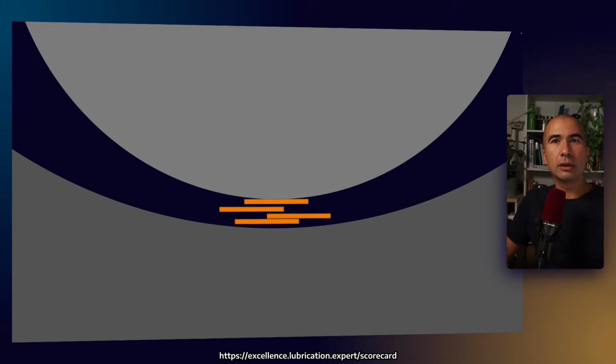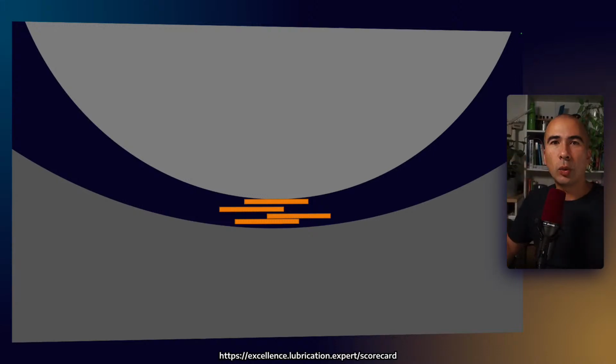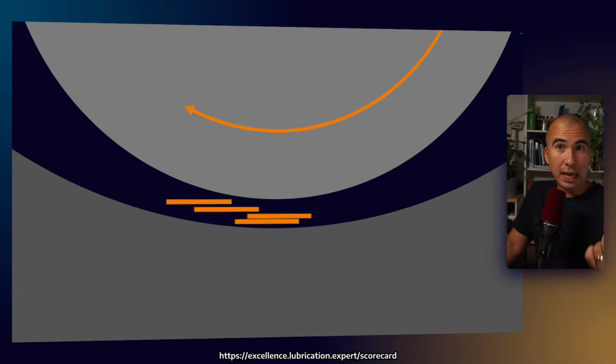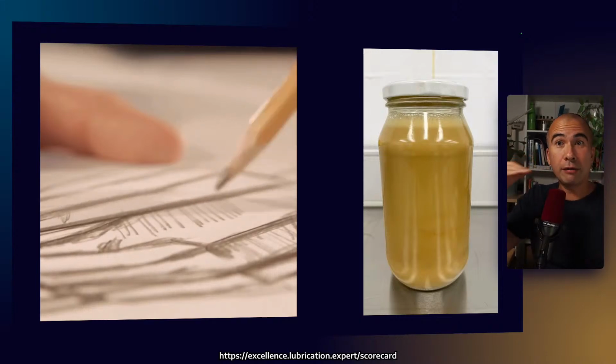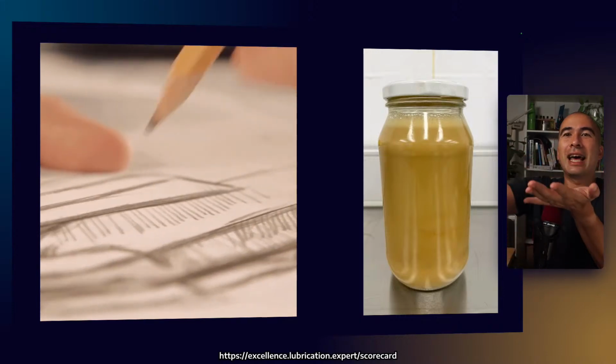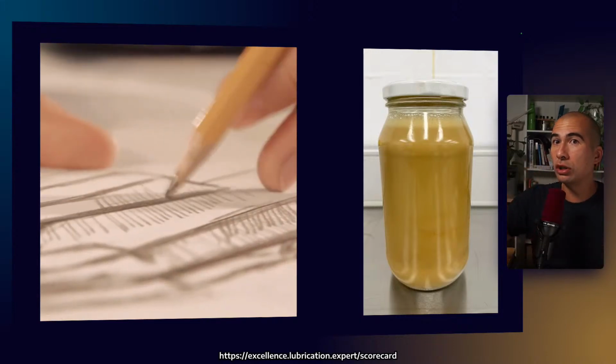All right, a solid lubricant is one in which what we like to have is what's called lamellar materials. So they have atomically thin planes which have very low shear strength between them. So when we get this kind of rotation, right, the planes like to move across each other. One of the easiest ways to demonstrate that is when you use a pencil, right? Graphite is a solid lubricant, and it is layers of graphite which are sliding off and depositing onto the paper. So that's why the pencil motion is very smooth, and it's how you get the graphite to deposit onto the paper.